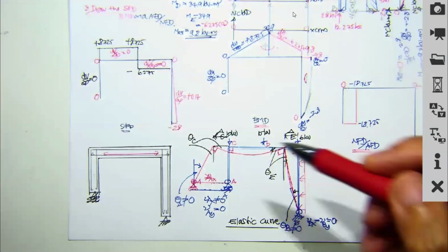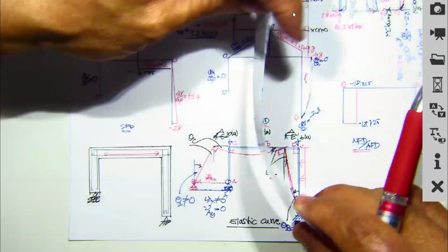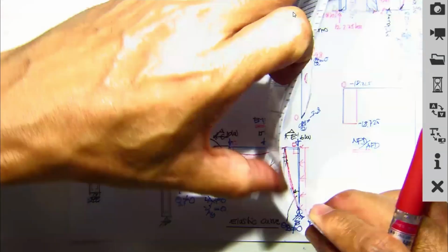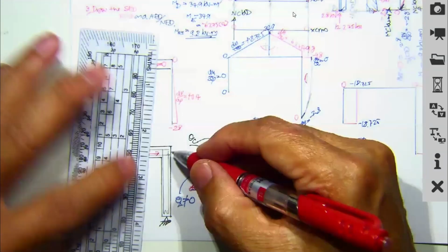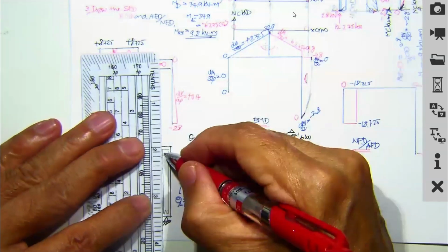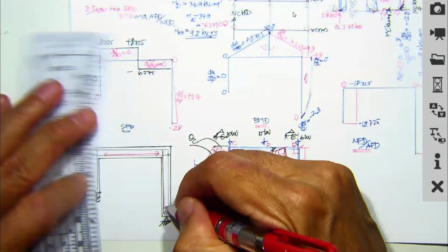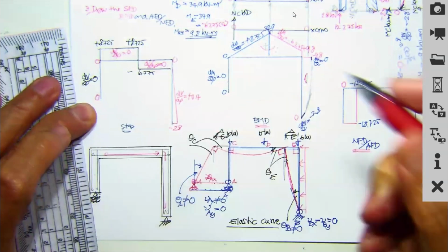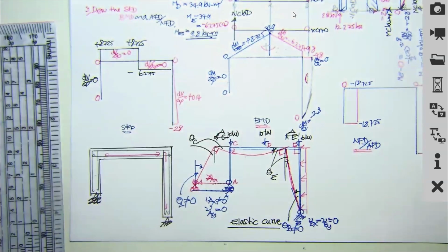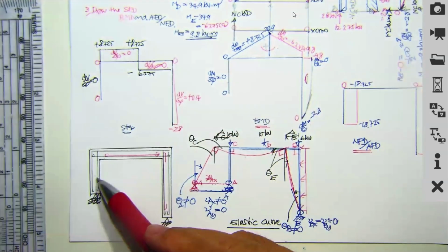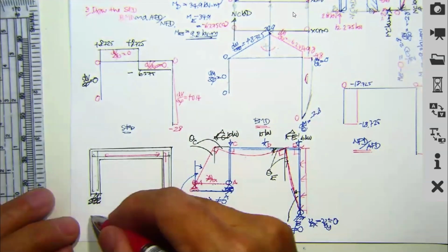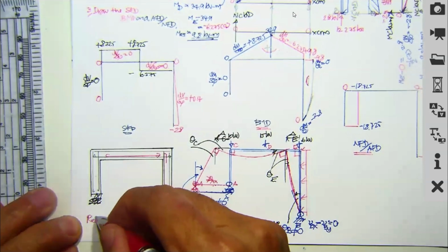This one also is going to bend like this one. This surface is going to be in tension. So for this one, you may put the steel, extra steel, only for this, the red. No need for this one. This is for reinforcement.